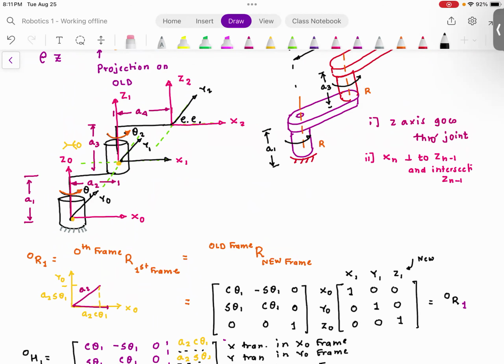And why are we getting identity matrix? Because when we started, we assume x2 is in the same direction as x1. If I would have assumed x2 is the opposite direction of x1, then the negative sign would have popped in. And then to find the actual rotation matrix, you have to multiply these two matrices. So there is one more matrix multiplication.